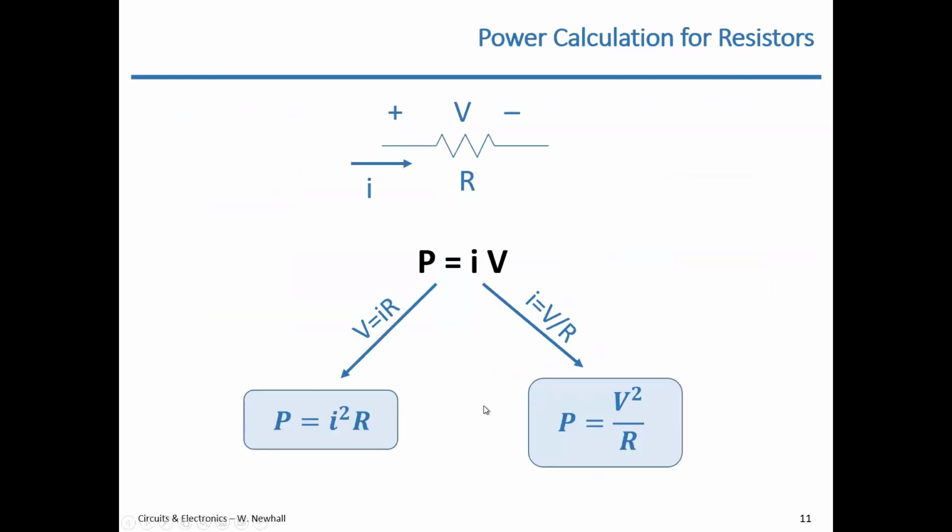So let's go back to this. Let's talk about this calculation right here, I squared R. Let's suppose you have a negative current. If you square the negative current, like -2 amps, you get +4, so +4 times R. Whether current is positive or negative, power always becomes a positive value for a resistor. That's really important. Power is never negative for a resistor. Look at those squared relationships. Even if the voltage is negative, you square the voltage and get a positive value. So P is always positive.